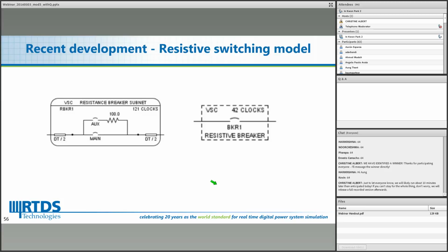So we've been aware of the characteristic of LC switching, and on the left side we have a single-phase real circuit breaker model with a pre-insertion resistor. A real circuit breaker means that it's an R-on, R-off type approach based circuit breaker. So we can make our power electronics simulation closer to the real-life system by using this model. And the right side, this is the real G value switching model without this half time step interface lines. So this circuit breaker or the switch model can directly participate in the G matrix manipulation business.